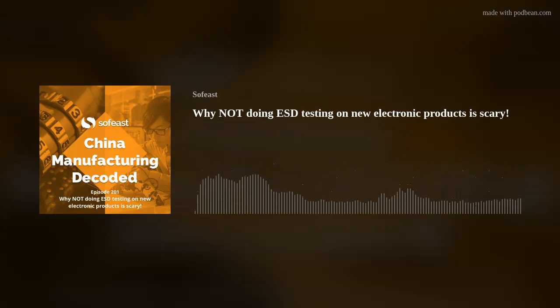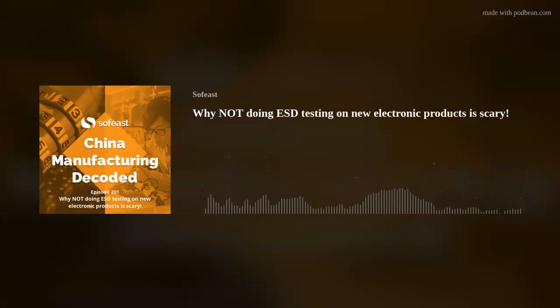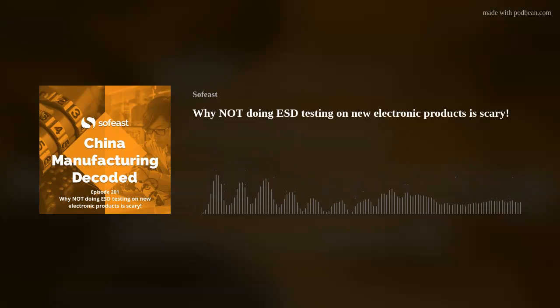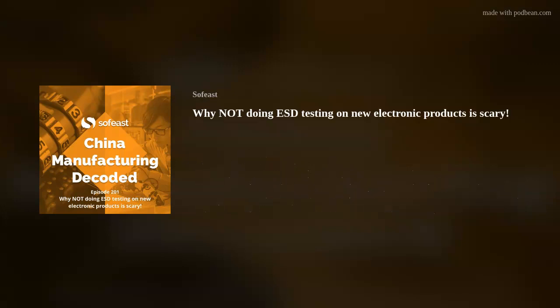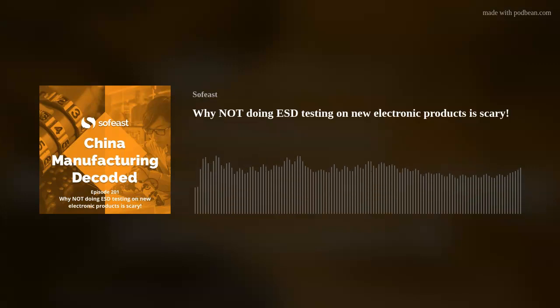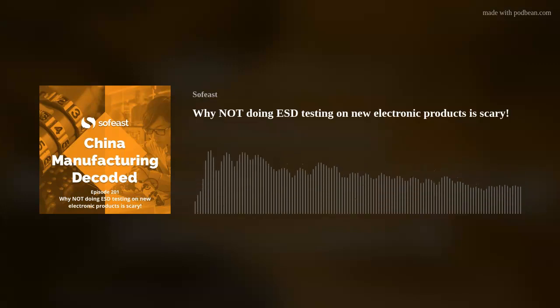Then you need to definitely test it. A quick test doesn't cost much. When your prototype is ready for reliability testing, at the end, after you've gotten all your design data, including reliability data, you can do two more tests real quick: a compliance screening test, and also an ESD test. These two, along with reliability testing, will bring out and detect all kinds of issues that you could have as a result of reliability, quality, ESD, and compliance. You need to cover all of these during your design and development phase.